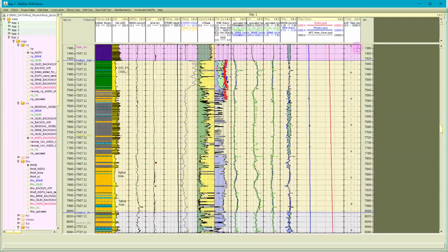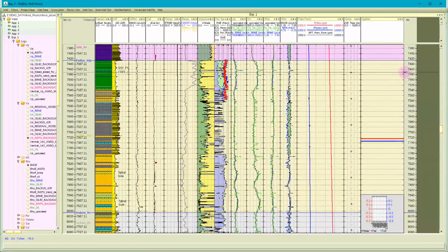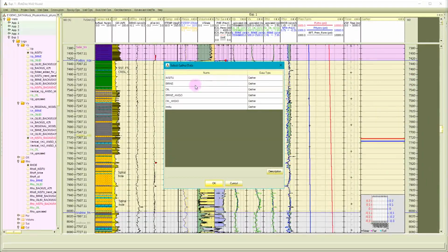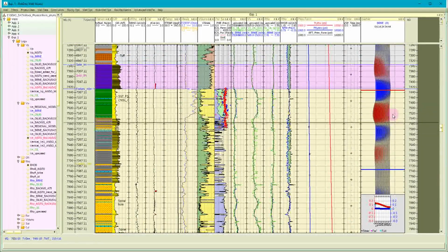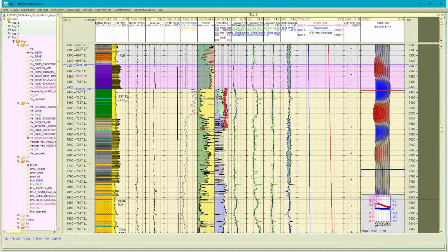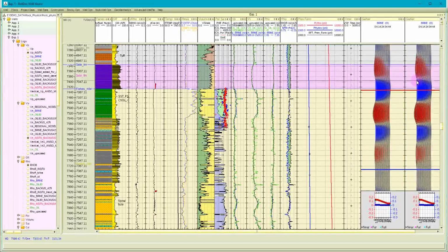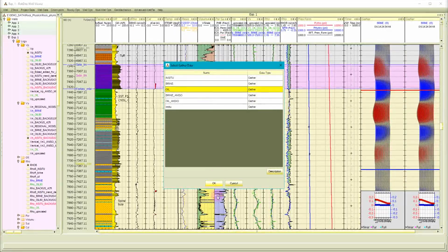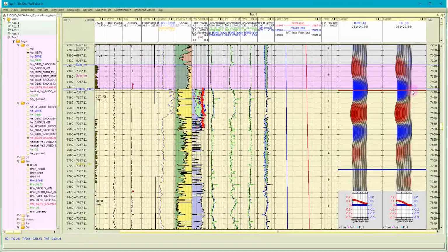Once synthetic gathers have been generated for a number of scenarios, they can be displayed within the well viewer and amplitudes extracted at any interface. The AVO response at the top of the sand unit is now being shown, and the AVO is plotted in the lower attribute plot. Multiple gather tracks can be shown with different fluid cases in each. The brine and oil saturated cases are shown now. The extracted AVO for the top of the sand can be compared between the cases in the attribute plots, which show amplitude versus angle here.